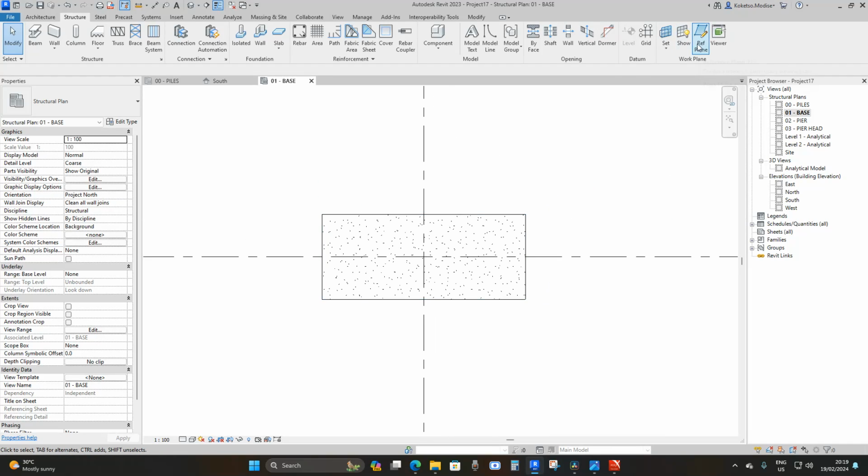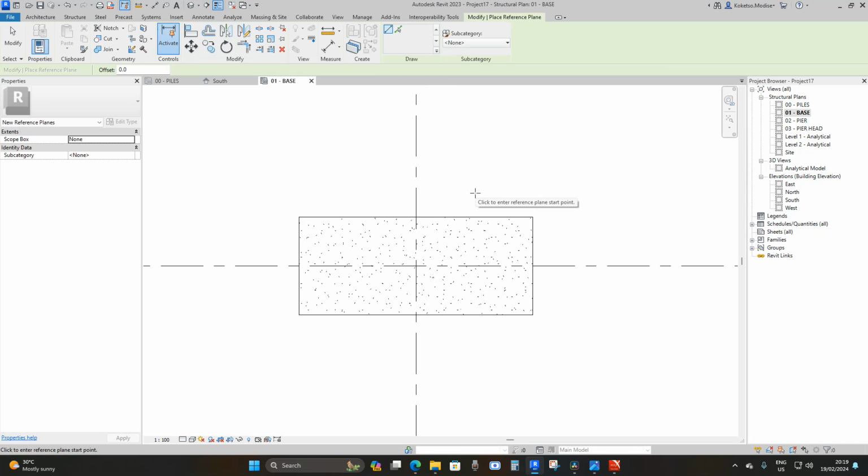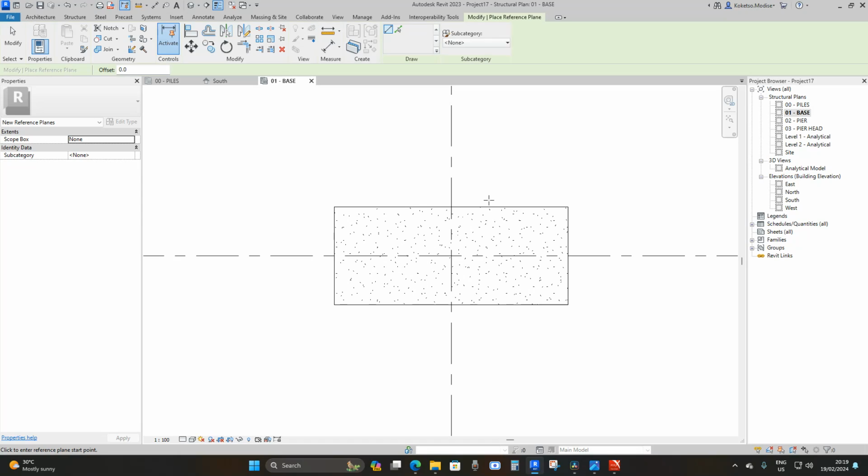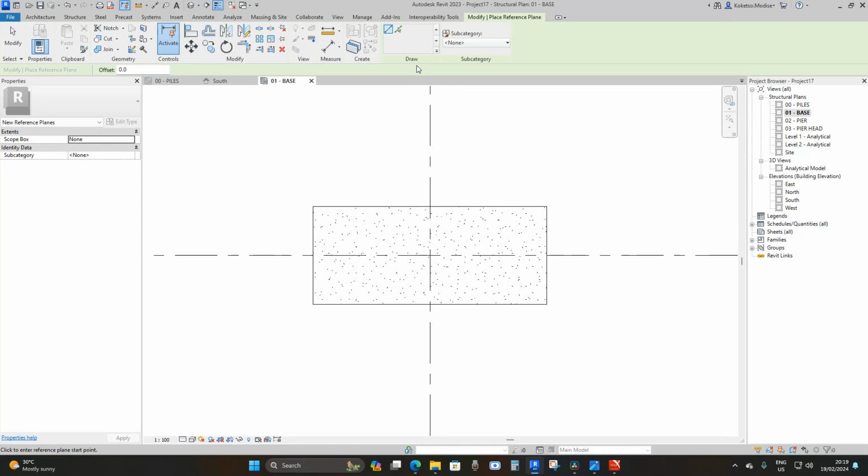And now we're gonna select our reference plane. We're gonna use them temporarily. We're gonna remove them after we place our piles. So from the center, you're gonna say pick lines and then create your offset. And then your offset from the center is gonna be 1750. And then you're gonna pick your grid and then offset your reference line. Perfect.